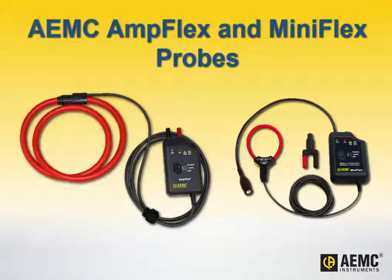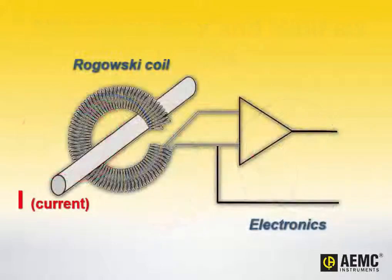Some of these probes include electronics to provide a stronger and linearized output signal. The diagram on the screen illustrates how these probes function. In this diagram, the probe's Rogowski coil has been placed around a conductor. As current flows through the conductor, it induces a voltage, called V1, within the coil.